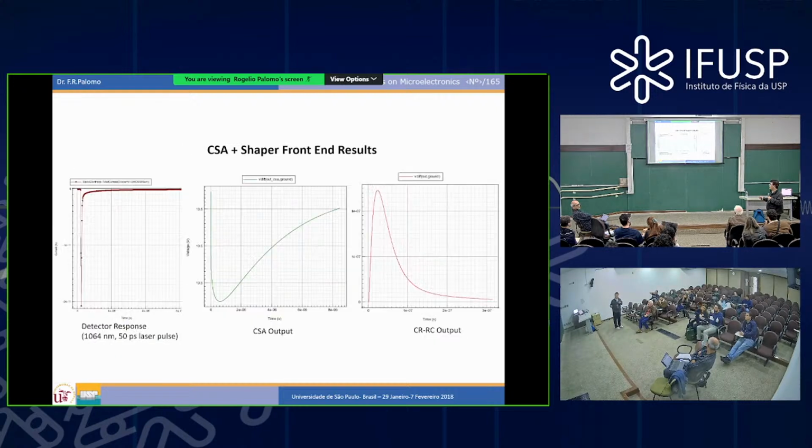Yeah, basically the charge sensitive amplifier is integrating this signal, and for ulterior signal processing you want to recover the shape. That's the reason you use a shaper here. Also, the shaper is a filter, so it takes out any possible electromagnetic interference effect that you will have in any real situation. So that was just a test to know if not only the detector, but the whole chain was sensible, that the design was sensible enough to go further.